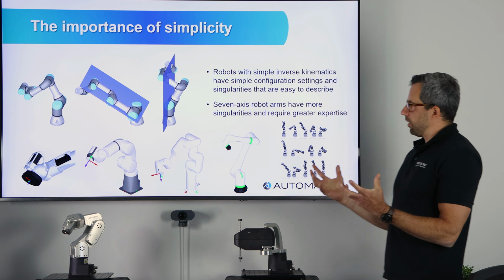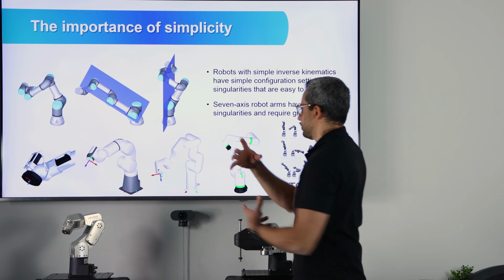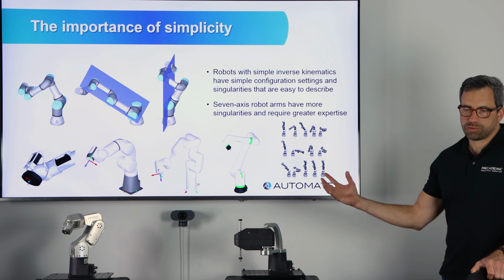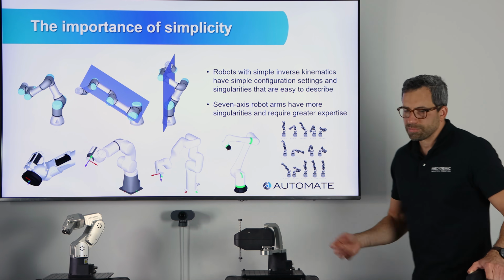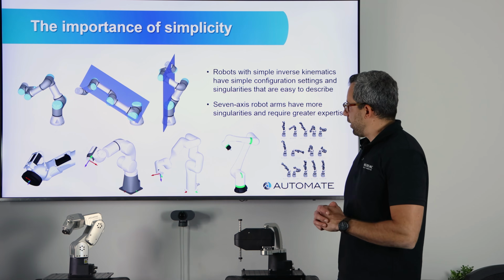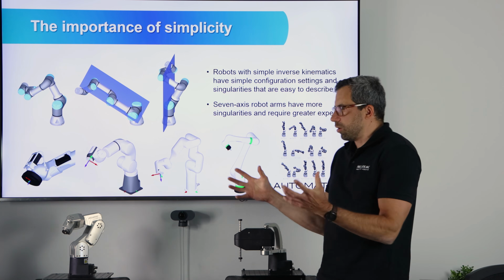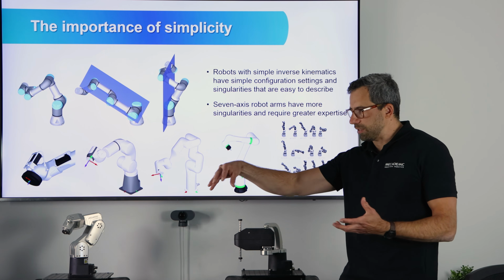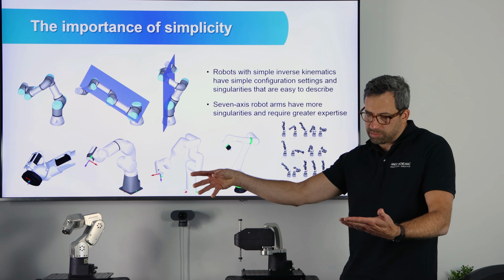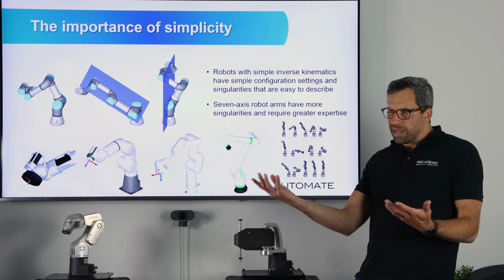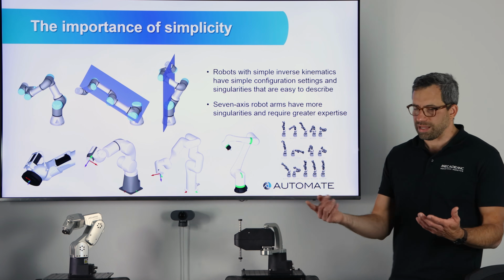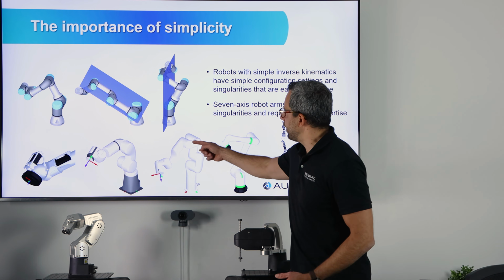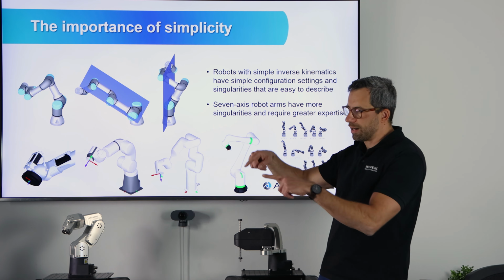So first thing, if you have this kind of special architecture, you cannot use software like RoboDK. Also, you no longer know where the robot is in a singularity. You move, and then suddenly it stops, and okay, it's a singularity. I didn't know. Why is it in singularity? You don't know. You cannot say, when axis 1 and 2 are parallel, or something like this.